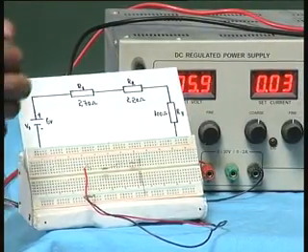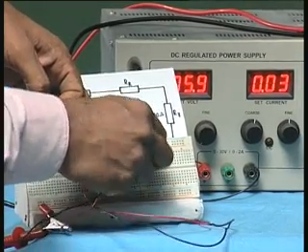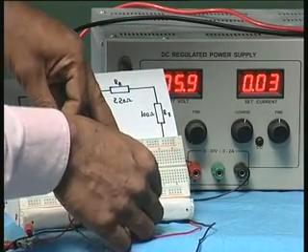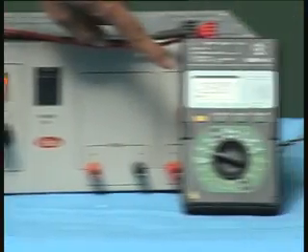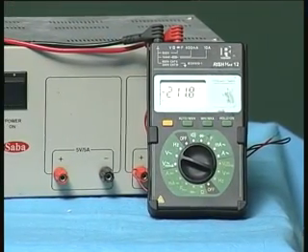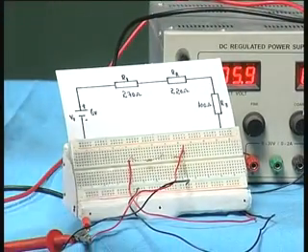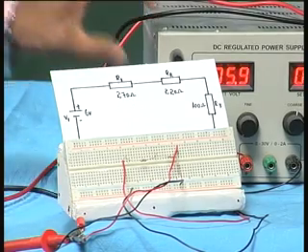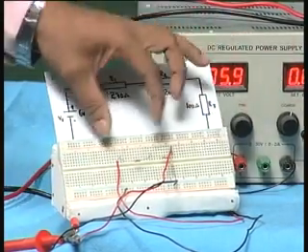100 ohms. I will connect the voltmeter across this 100 ohms here and at the bottom, and you can see the voltage is about 1 volt. So, totally 2.77 plus 2.24 plus about 1 point something together gives me 6 volts approximately. So, you can see whatever voltage I connected here is divided across each of these resistors.